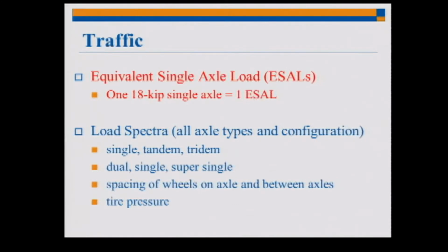Traffic, you can assume ESALs or a load spectra analysis. Generally, we use ESALs, but the design allows you to use a load spectra. So it doesn't really matter how you characterize the traffic. Both the methods work pretty well.